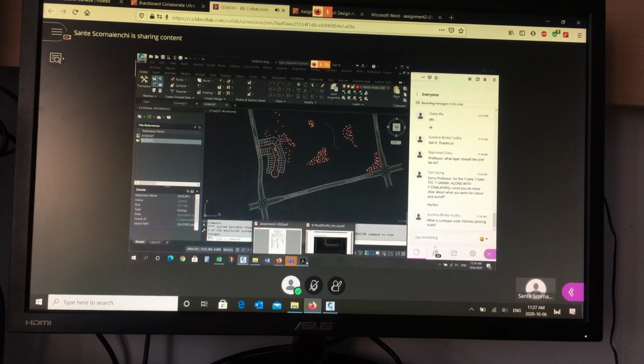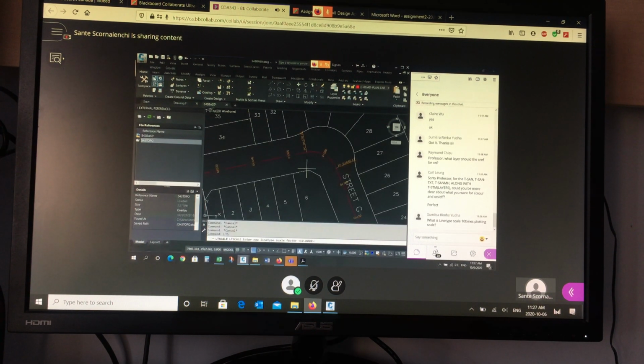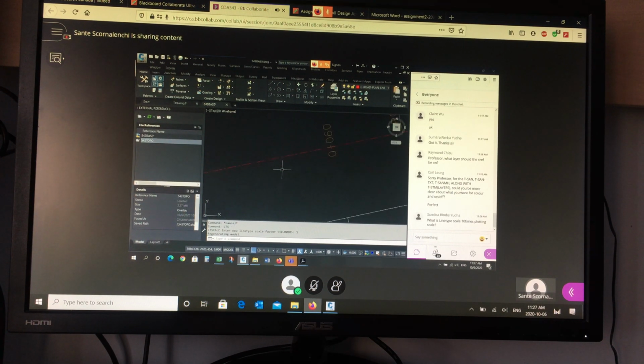What is line type? Okay, I'll show you. See my centerline line type, this red dash thing? If I type in LTS, watch what happens to the pattern. It's set to 10. Watch what happens if I set it to 1. See how small it gets? The distribution of the pattern changes. LTS set to 5, you'll see the pattern changes, and LTS set to 10, it changes again. So it's the scale factor on the pattern of a line type. It does not affect the continuous line type. Okay? So that's what it does.